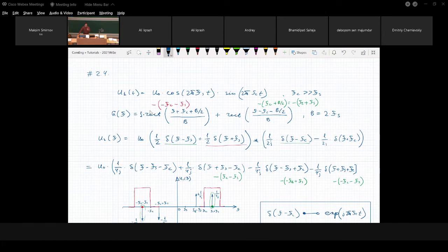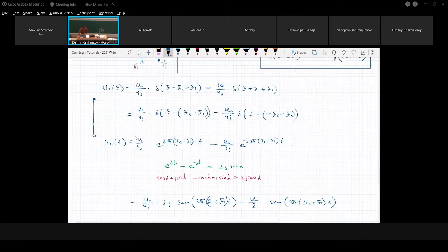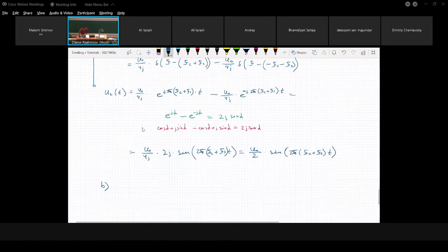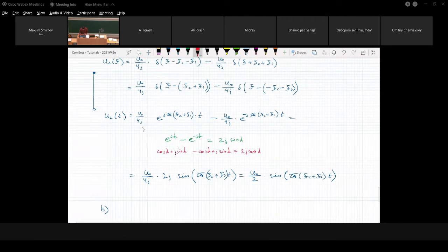But the product of these two quantities, or the area, equals 1. If we don't specify anything else, by default we say that magnitude equals 1. It is nothing else than the integral of the delta pulse, say in the frequency domain, from minus infinity, which equals 1. It's area. This is magnitude. We distinguish these two quantities, magnitude and amplitude, because amplitude is infinite.